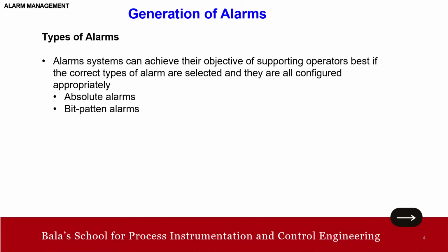Now, bit pattern alarm, it's a digital one, right? It is generated when a pattern of digital signals matches a predetermined pattern. Okay. Then calculated alarms. So this is generated in software based on a logical combination of several signals. So that is the point. Okay. Then system alarm.